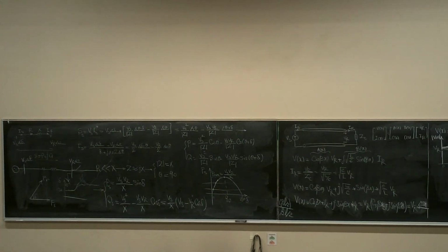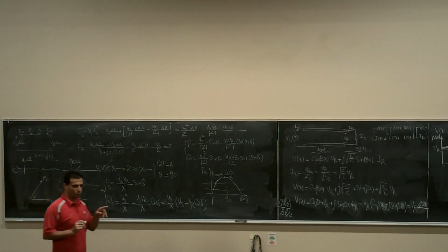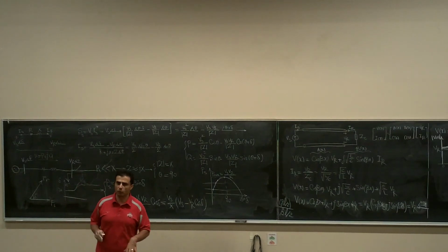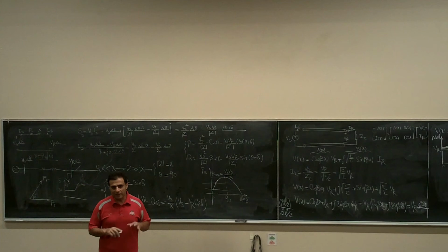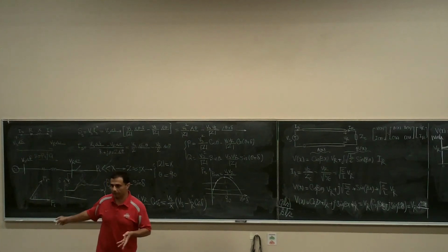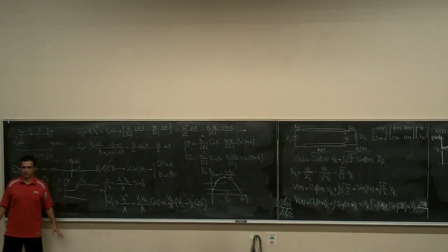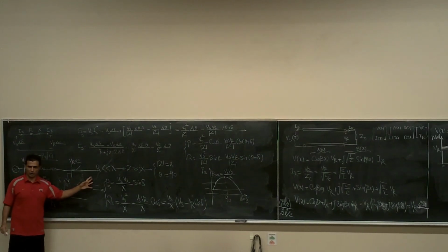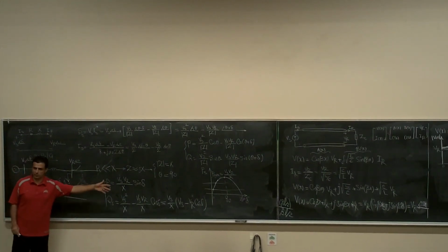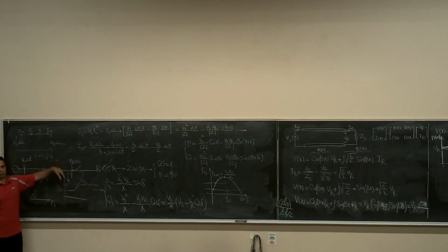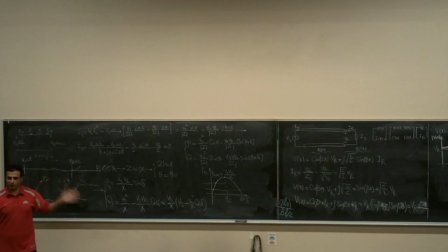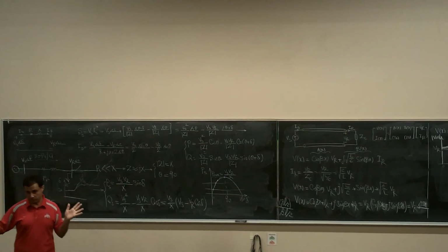Nowadays, they are trying to use this concept they call group control. If you are interested, just type it in Google and it'll bring it up for you. Group control is a new mode to control this inverter. They're going to say, hey, I'm going to be like a generator. I don't care if the grid is there or not. If the grid is there, I'll follow this equation. If the grid is not there, I'm going to support my load. You know what I'm saying? There is no transition: grid off, grid on, grid off, grid on. It's a big transition for inverters.